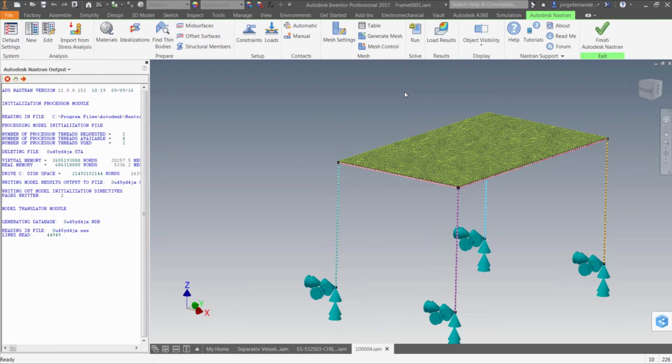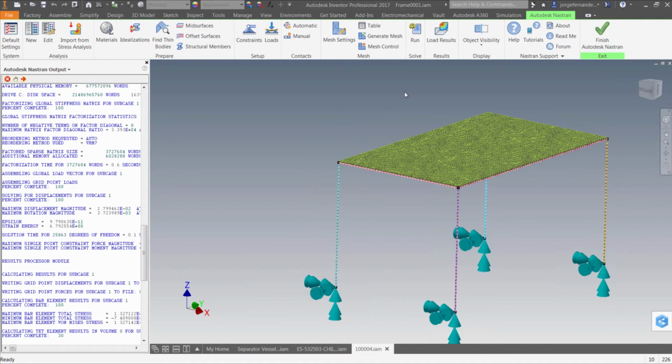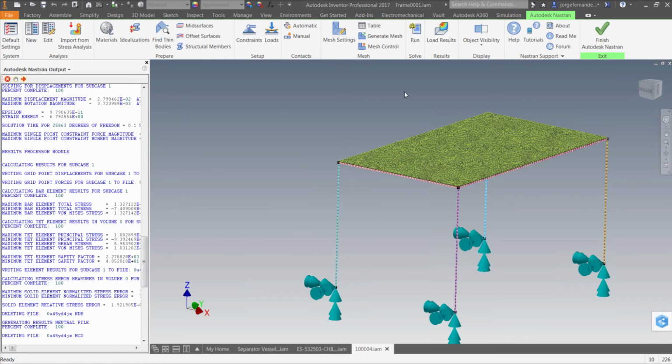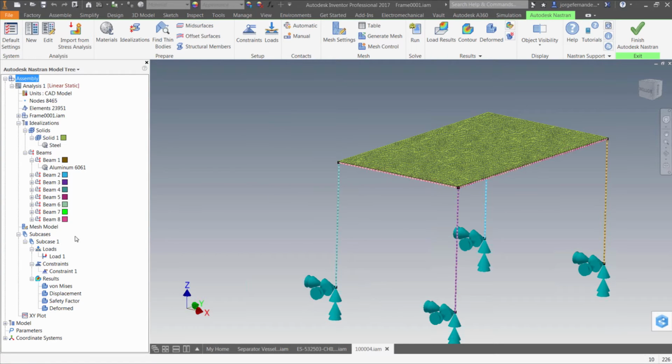What you'll notice is it runs again right inside of Inventor. It runs really quickly, so we can see the results pretty instantaneously, I like to say, without having to exit Inventor at all. Just change that environment. I'm able to now go over to these results and look at them. For example, let's say I wanted to look at the overall stress with the von Mises. Von Mises, I called it the first time, but after that, I never called it von Mises again.